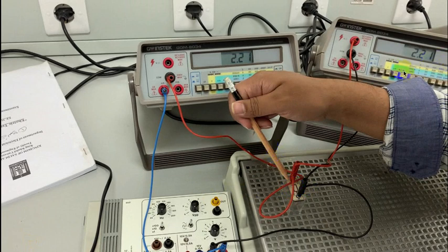So here the voltage is 2.21 volt, not kilo or not milli, it is volt. And here you can find exactly 2.21, but it is in milliampere. So when you multiply V equals to IR, what is my V? 2.21. I is 2.21 into 10 power of minus 3. What is R? 1 into 10 power of plus 3. 10 power of minus 3 and plus 3 becomes 0. So V equals to IR is proved.